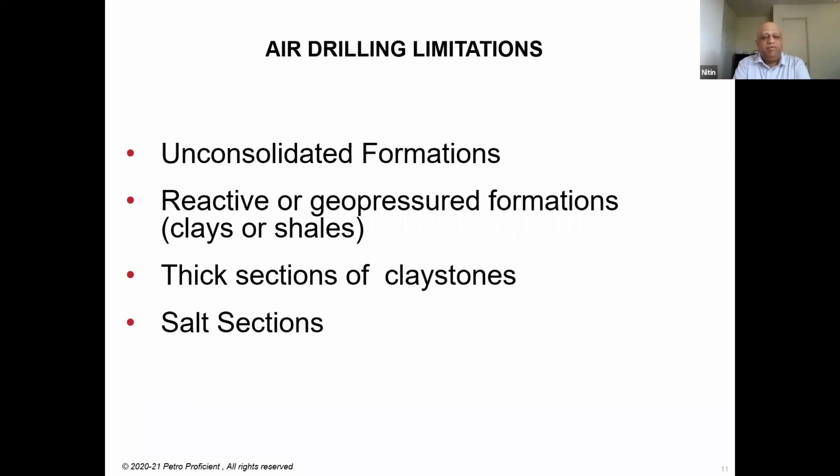So you really need to have a very hard formation, a formation with a lot of strength, in order to ensure that it doesn't collapse. Formations that are unconsolidated or poorly consolidated, we cannot use this technique. So it requires some kind of initial engineering evaluation to ensure that the formations have enough strength to be penetrated and balanced. The other thing that you want to ensure is that there are no reactive or geopressured shales.